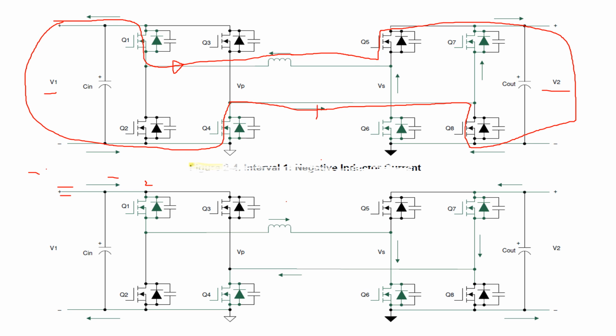second interval, when the switch of the secondary side is changed from Q5 and Q6 and Q7 to Q5 and Q8. So the direction of the current is positive, and that's the flow of the current in the DAB.